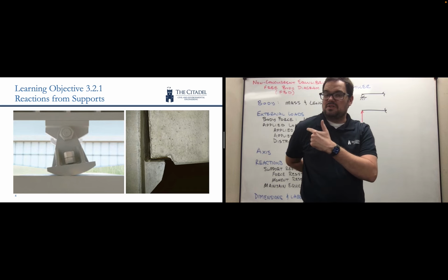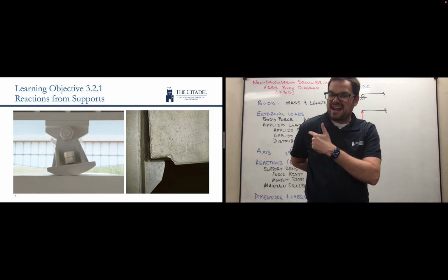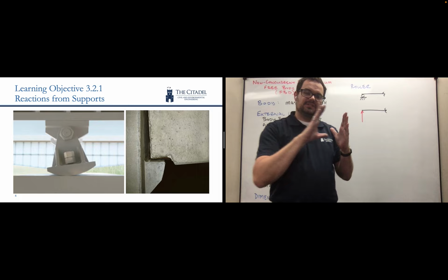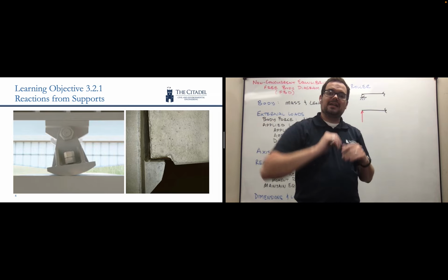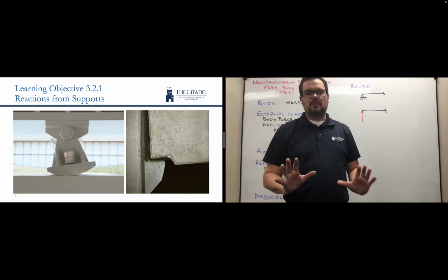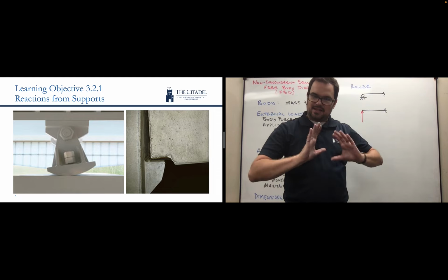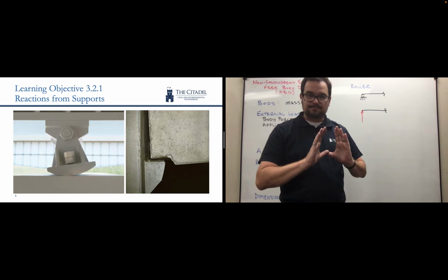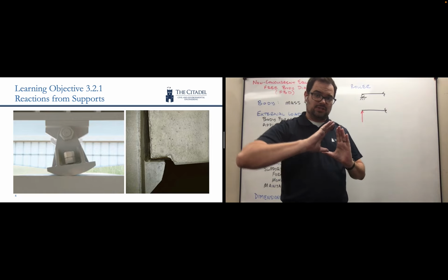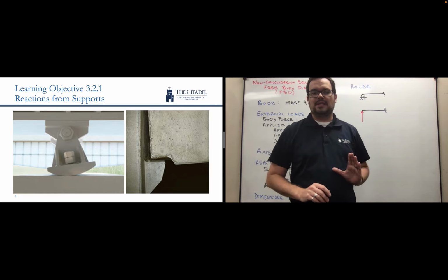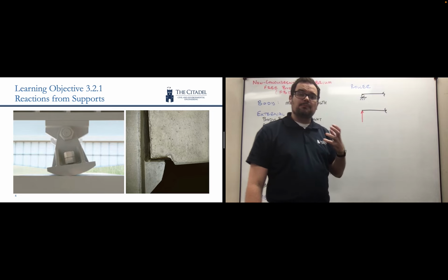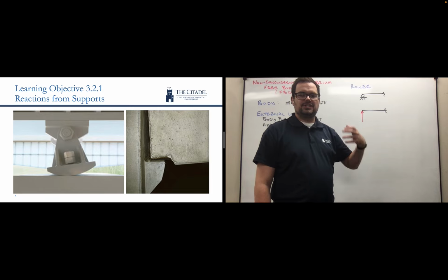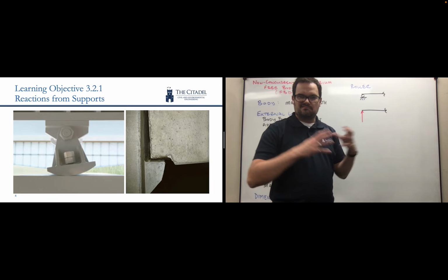And so when we're doing our designs, we want to make sure that our structures are kind of happy about what's happening to them. So in this example, if that beam was to slide to the left or to try and rotate up, we're now working outside of what we want the beam to do. We want the beam to just sit there, and if it's just sitting there, there'll be no lateral translation resistance and no resistance to rotation. It'll only have resistance from that little key in the vertical direction. So that's an important thing to think about when we're trying to build these mental models, is that we want to look at the connections within their normal working range.